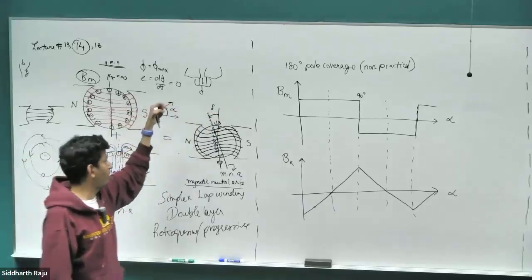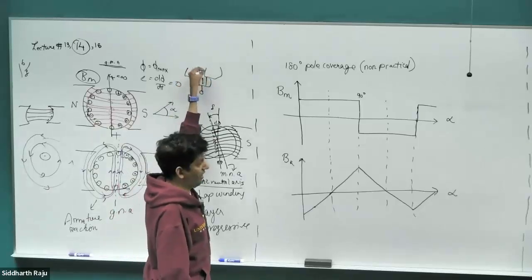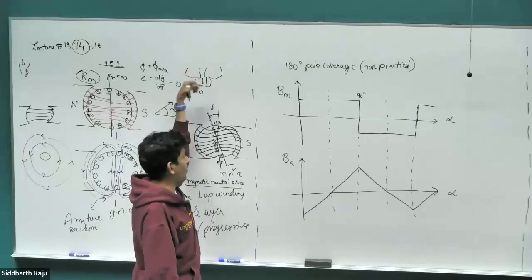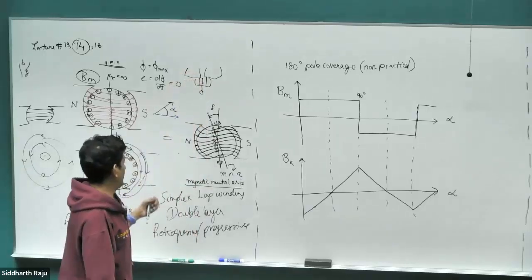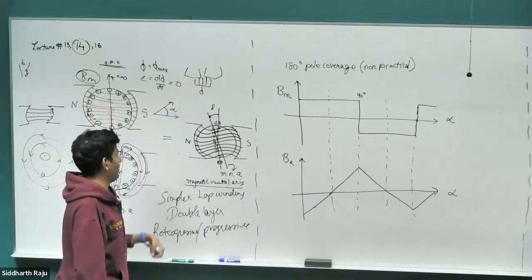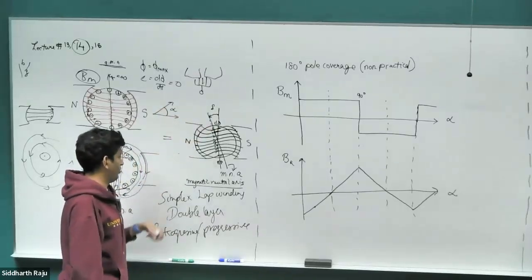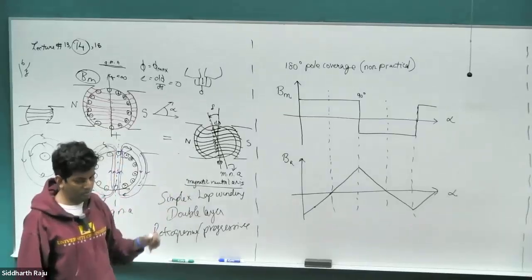So there's going to be a huge amount of current that goes through these coils, through the graphite brushes and start to eat away at the graphite brush, as well as damage the coil if the current ends up being too large, right? Which can be the case when the motor operates at very large speed because the EMF induced is not negligible even at those angles very close to 90 degree. Can anybody tell me what the solution for this would be?